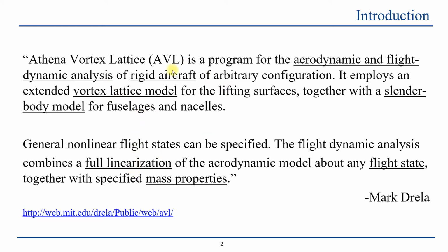Not only can you run some aerodynamic analysis with the software, you can also do some dynamic analysis or stability analysis for your flying objects or aircraft designs. For that, the general nonlinear flight states can be specified in the program, and the flight dynamics analysis combines a full linearization of the aerodynamic model about the flight state together with specified mass properties.